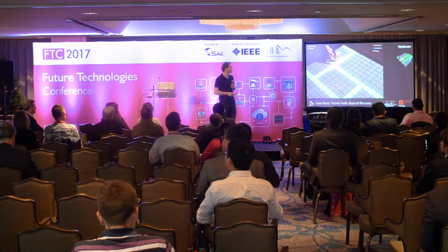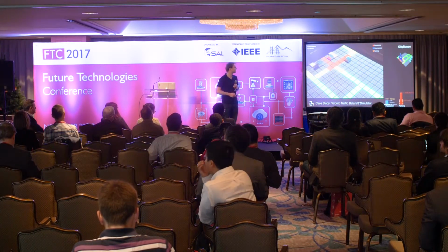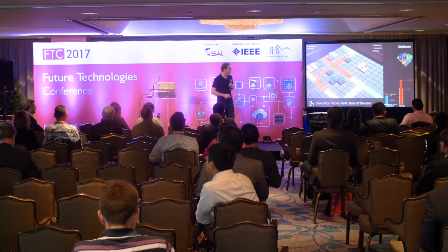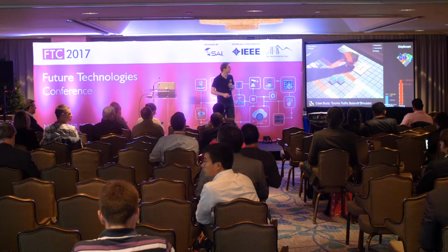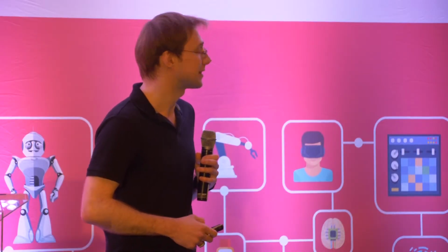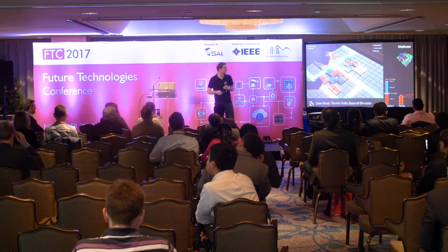So you can see as you place only commercial use here, you see traffic balance kind of getting out of whack. You need lots of parking. But if you were to theoretically provide now residential in equal measure, you can start to see this balancing effect, where if you create trips within the city rather than in and out of the city, you actually have a lighter load on your roads, theoretically.